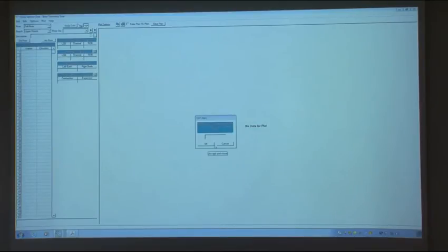Now a small window pops up for a new river station for the new cross-section in the upper reach. Okay, so now we are going to enter the river station as 10. As we mentioned last week, HEC-RAS uses a system to name the cross-sections as real numbers. The cross-section with the highest number is by default upstream. It's a real number, so you can do 10.1, 10.2, and so on. But right now, this is cross-section 10.